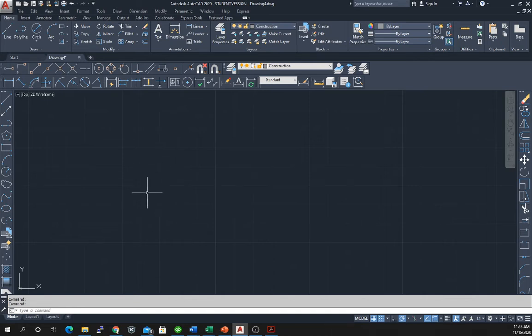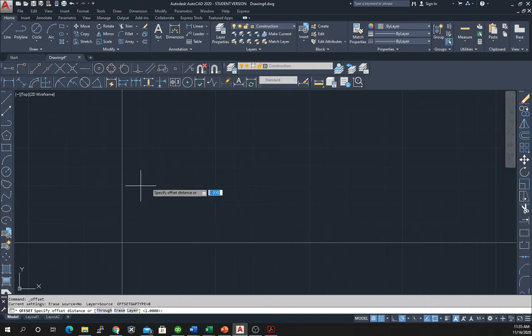And if you have your book, if you look on page 5.7, we're going to set up some construction lines. I'm going to start right here and just set up a pair of construction lines. And now we're going to actually use offset to set up our additional construction lines. So we're going to set up another vertical construction line 5 inches over.